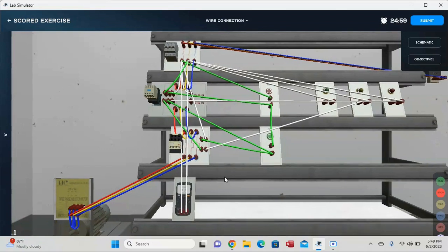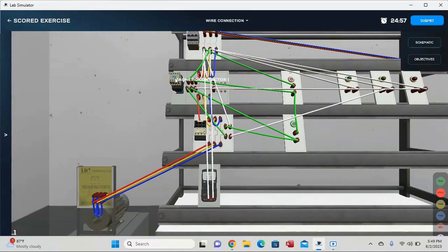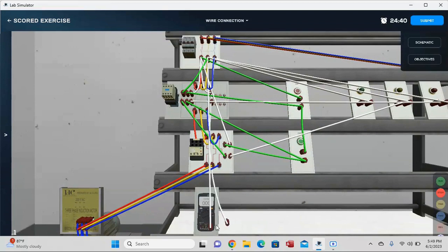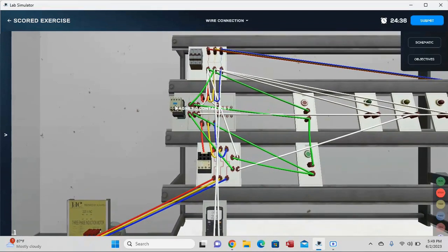Okay, so we have this reading, and we need to press the magnetic contactor a few times just to be sure that the reading should just be the same or should not be less than 1 ohm. Okay, after terminal 2 and 4, we need to carry out terminal 4 and terminal 6. Okay, then check the reading.